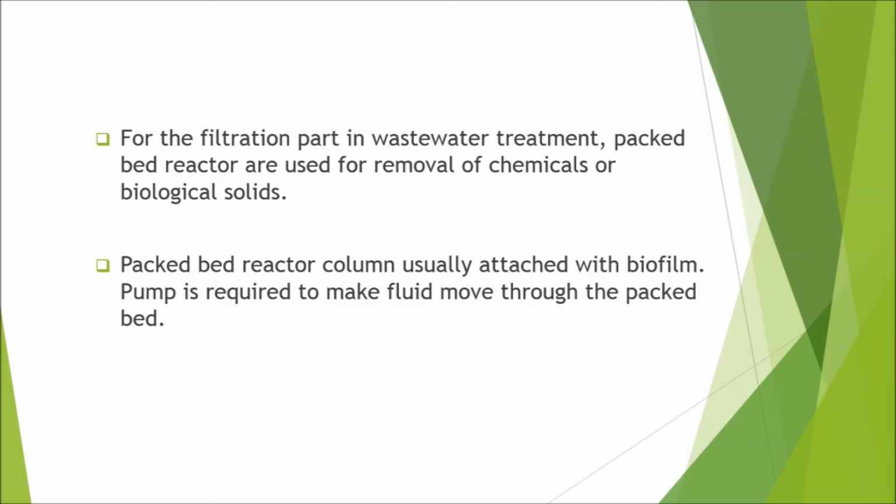Packed bed reactor columns are usually attached with biofilm. A pump is required to make fluid move through the packed bed. In this case, sand was used, mixed with other substances to filter the fluid, and sand is cheaper and non-fragile but requires a significantly longer time for fluid to pass through.